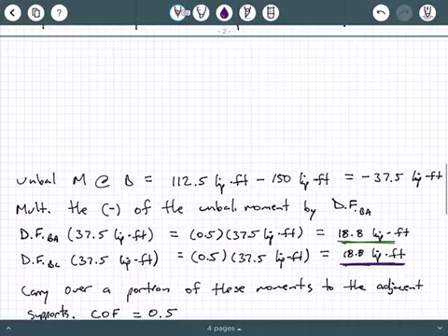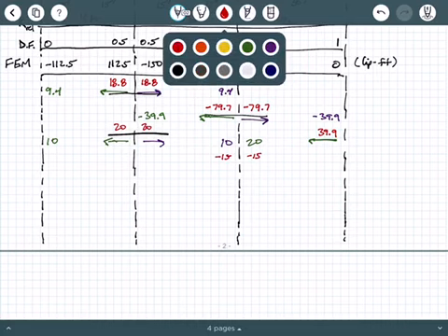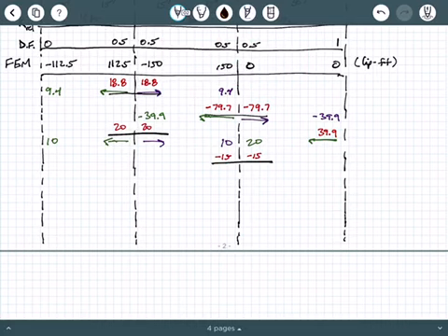Scrolling back up to my table that I'm populating, I'm going to put my negative 15s here that I just calculated. That's what balances off C, it is balanced now. And half of the negative 15 just to the left of C gets sent over to B as negative 7.5. And half of the negative 15 that's to the right of C gets sent to D as negative 7.5.